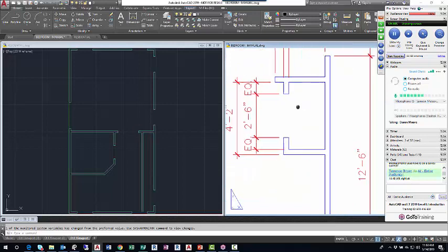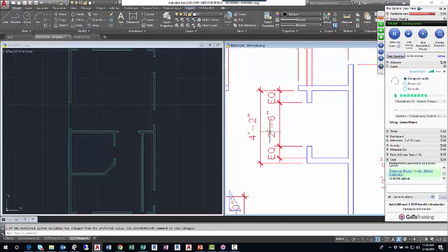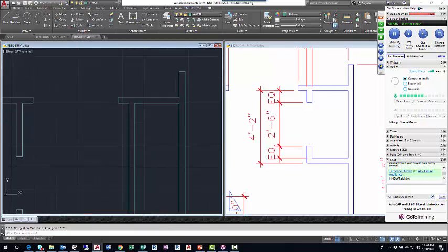All right, so I'm zooming in so I can really see this other closet. This closet is tricky. It's often tricky in class because most of the offsets that we're doing, we're going down screen, top to bottom, or we're moving in one direction. This one's going in two different directions. You've got an offset. I'll zoom in on this side. This bottom horizontal line gets offset down 4 feet 2 to make the bottom line of this closet. Then it gets offset up 3.5.